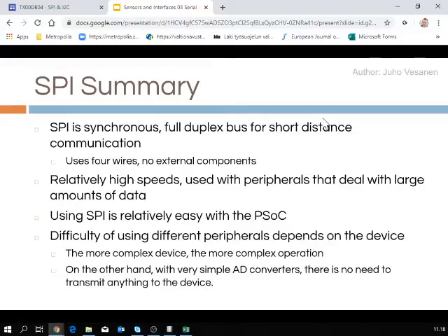Since it's synchronous and not that critical about timing, of course you can run one digital output as a clock with software, and then write another as a MOSI, and then have one signal input and read it as a MISO, have one output as a chip select. So you can do full software SPI. That's quite straightforward actually.